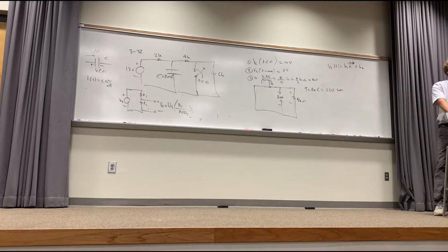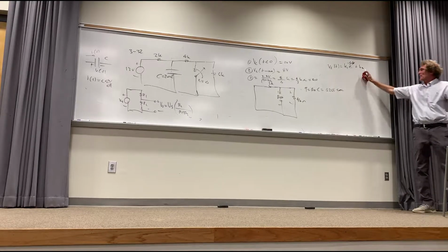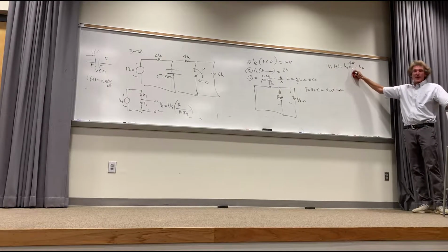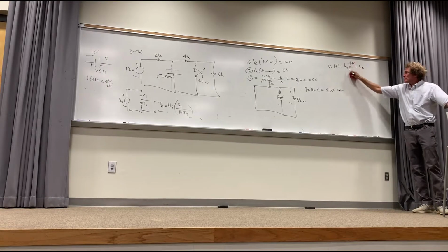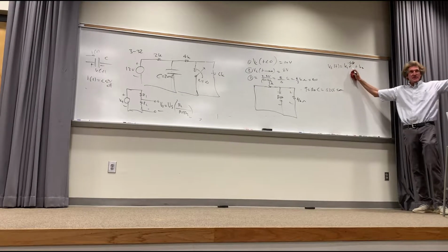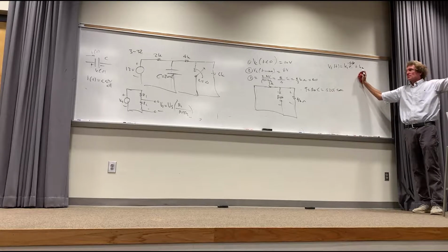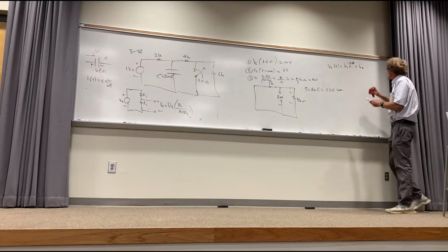What do we know about K2? That it's 8 volts. Voltage at t equal infinity, K2, right? And at 0, this would be a 1, wouldn't it? And you would have a K1 there. As t goes to infinity, doesn't this go away, class? How many see that? So K2 is the voltage as t equal infinity. And that's 8 volts, isn't it? Can you all see this? That's 8 volts.